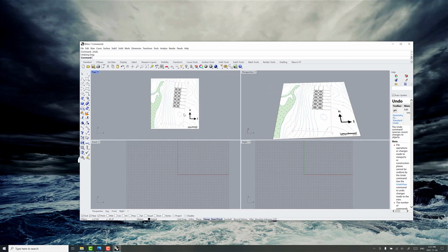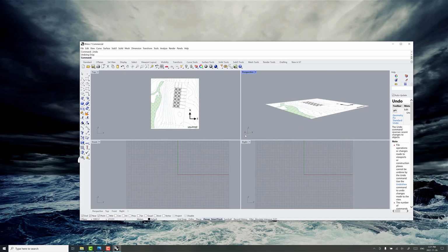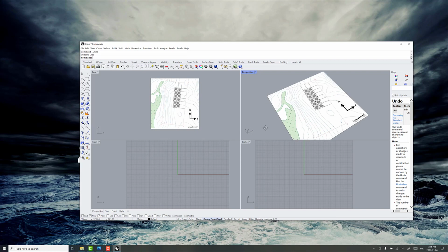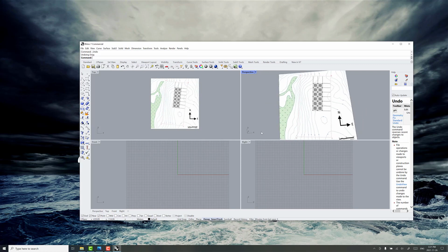The next step is to make sure that the northing and easting indicated in the chart actually line up with the ProteusDS coordinate frame. Remember, the Rhino coordinate frame doesn't necessarily mean the same thing as the Proteus coordinate frame. In Proteus, X and Y are on the calm water surface with positive Z pointing down, positive X pointing in the northern direction, and positive Y pointing in the eastern direction. You can see we don't have that lined up correctly.